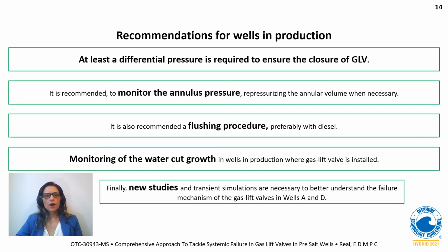If the gas lift valve is already stalled, check the absolute pressure and the differential pressure that the annulus is subjected to. There is a possibility that the valve is open, making possible the contact between the annulus fluid and the produced fluid, which brings a high scale deposition risk. Elaborate a flushing procedure with diesel as a first step after determining the annulus tubing communication. It aims at removing small residue that can be accumulated in the valve, which may prevent the closure of the check valve.